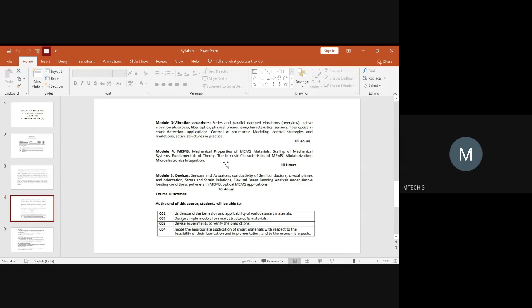Suppose you are making a MEMS cantilever beam, what is the procedure you follow right from selection of the substrate, adhesive layer, and then pattern making with the help of photoresist, negative photoresist, and how you etch out the remaining part, and how you do the packaging, and finally device making. So you can refer that for any micro cantilever or any other application.